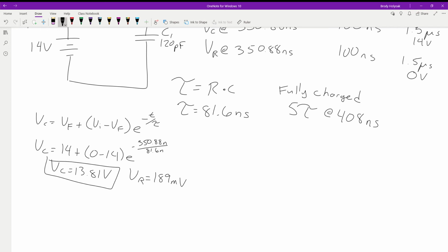Anything that comes in at 60 hertz after you've amplified it and turned it into DC, it just filters right out. Because if not, you get this noise, and you're going to see that on some of your circuits because they're not going to be grounded properly. They're not going to be filtered, and you'll get these really weird harmonics sometimes. So when you start working with 120 hertz, 240 hertz, anything that's divisible by 60, you're going to start seeing these 60 hertz spikes come in every so often, and it's going to completely throw off your measurements.